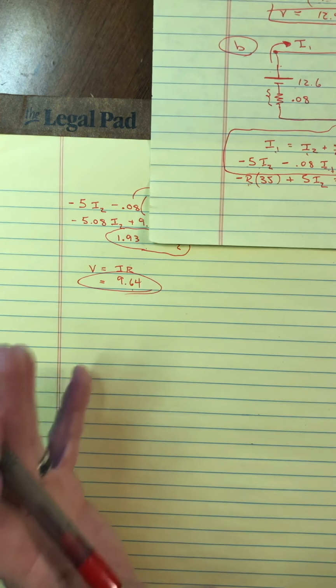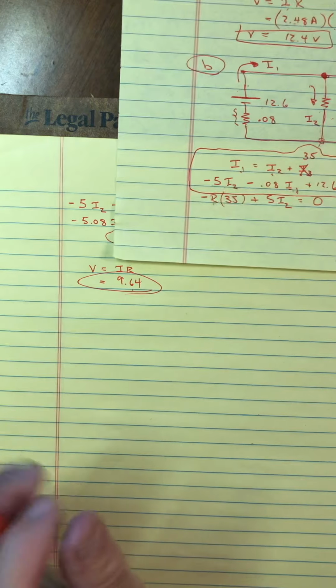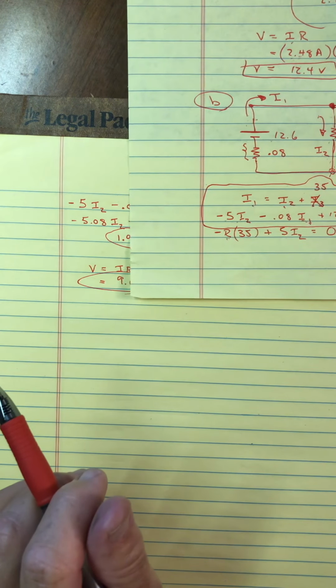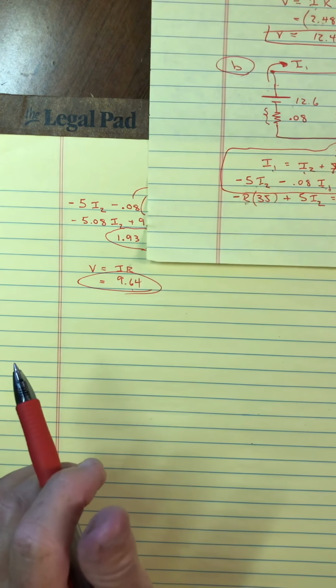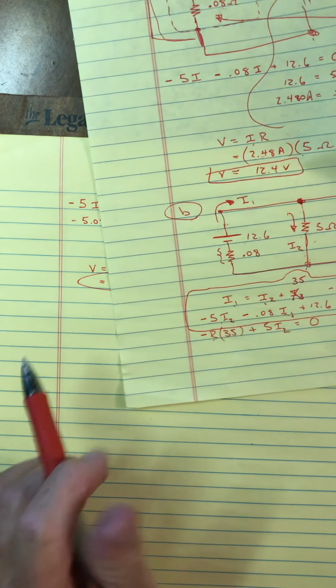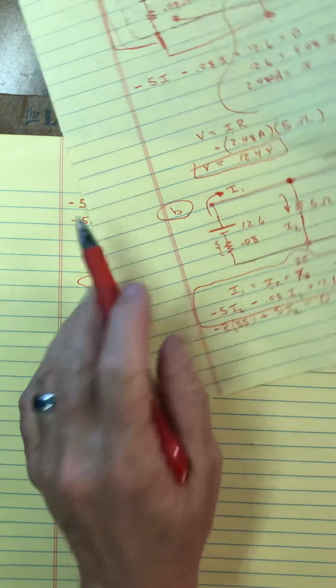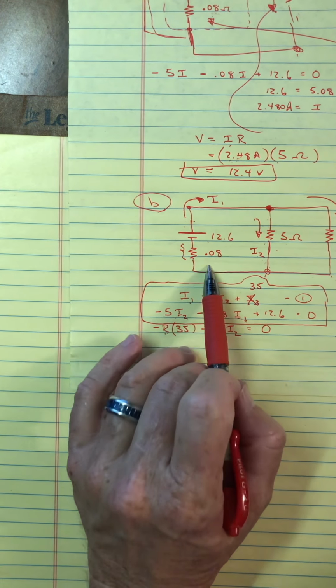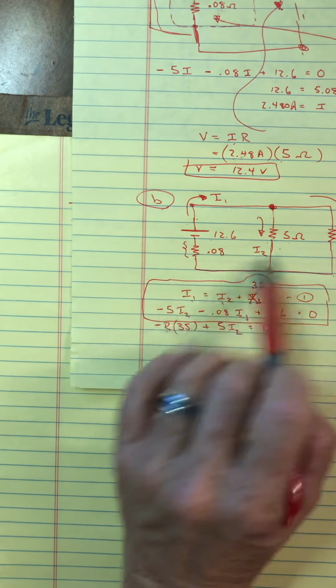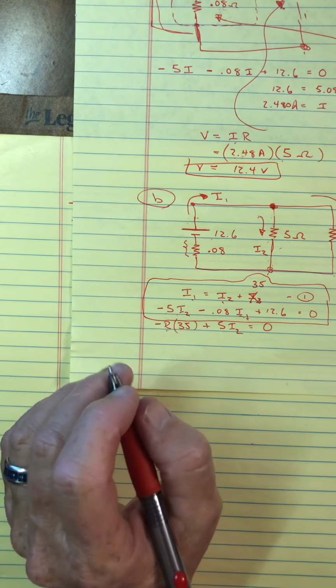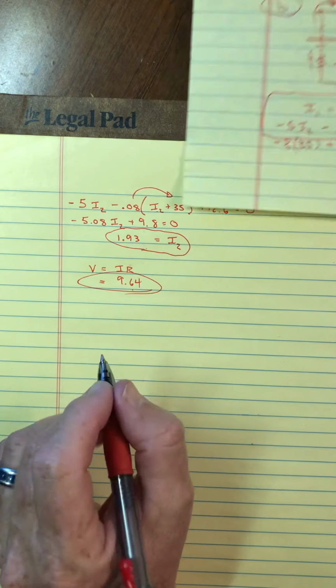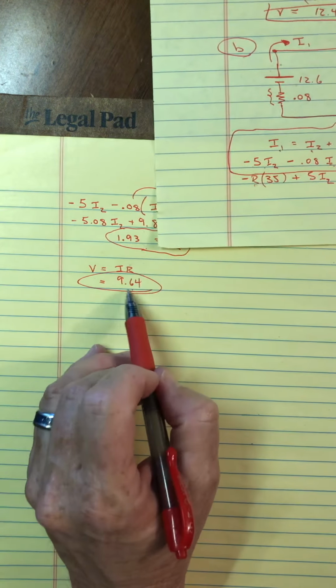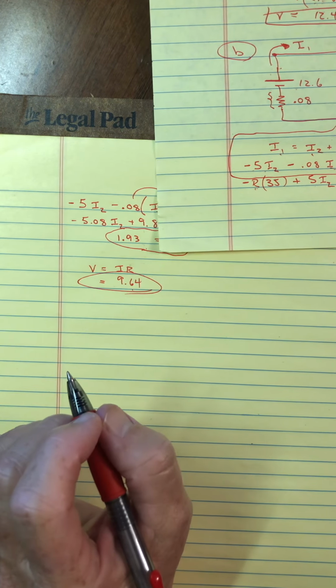Probably still enough to start your car, but, like I said, it's taking a lot of strain on the battery here. Of course, it's a pretty high internal resistance for a good lead-acid battery, so I'd say this is not that great of a battery. It's not bad. It probably still starts your car, but probably within the next year you're going to need a new battery. Okay, so here is the voltage.